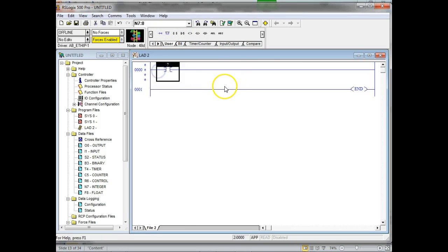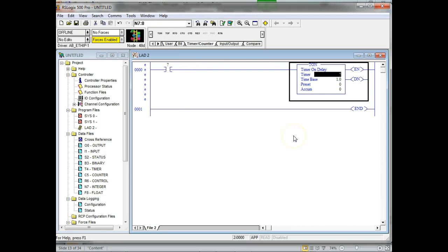Then we're going to insert a rung, and then insert an input so we can see it. This is our palette of instructions. I'm going to go to timers, and we're going to do TON. What type of timer is that? Yeah, it's an on-delay timer. I'm going to drag it down, and it pops over to the output instruction side. It's a one-input instruction. So this one input not only starts the timing, but it also does what? Disables it too.